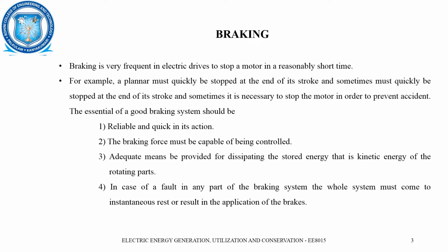Braking is frequently used in electric drives in order to stop the motor within a reasonably short period of time. For example, a planer must be quickly stopped at the end of its stroke, and sometimes it is necessary to stop the motor in order to prevent an accident. The essentials of any good braking system are that it should be reliable and quick in action, the braking force must be controllable, and there should be adequate means for dissipating the stored energy, that is, the kinetic energy of the rotating parts.